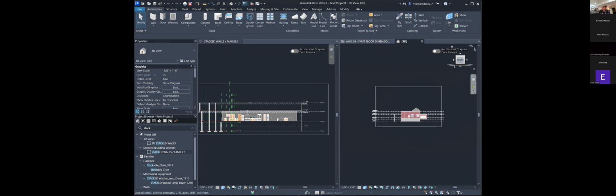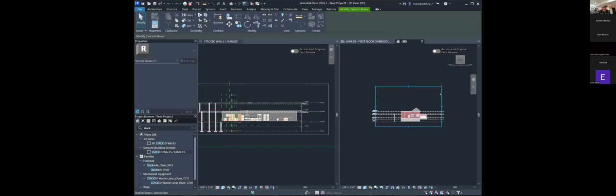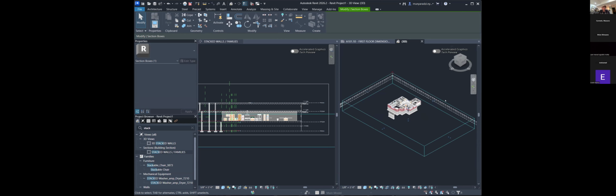And now we have that crop region. Click on that big box that's around there, and we're going to drag the top of it down. Go over to the left. There's a little icon. Drag that down right through the windows that you have there. Yep, right there. That's good. Now you can go back up and click on any corner of that view cube, and that will show us a view of your house.